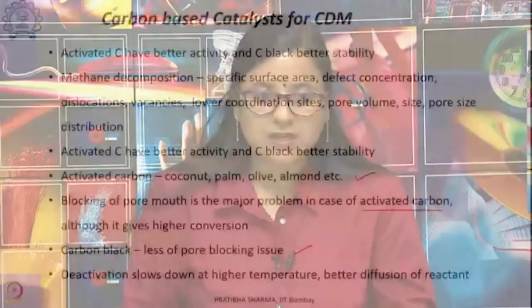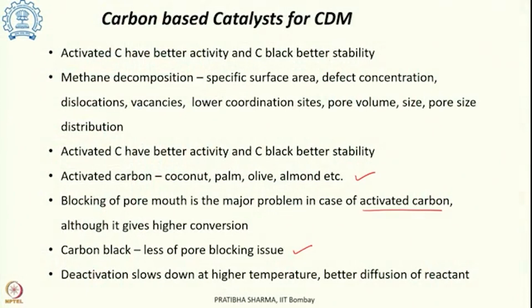Now, this deactivation which takes place with these materials is found to reduce at a higher temperature. The reason is, if the pores are partially blocked, then the reactant diffuses in a better way at a higher temperature, and that could lead to decomposition of the reactant.